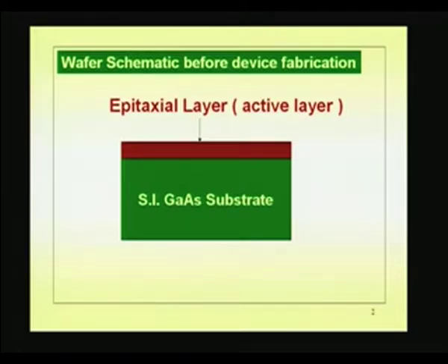If it is gallium arsenide, you must be able to transport gallium and arsenic, both should be transported onto the substrate. Okay. How to transport depends upon the particular process that you are using, and you call the particular process by a name depending upon how you transport these constituent elements, atoms. Okay. So, that we will see, what are the different processes which are involved.